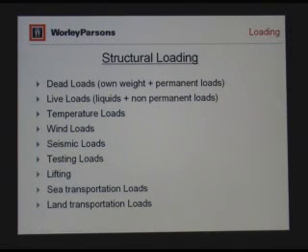But this has seen quite an evolution. Now, I think most of you are familiar with the seismic zones that we used to use in the Uniform Building Code. And as you may or may not know, the seismic zones are gone. They no longer exist. And what we have now are site-specific accelerations, the short-term and long-term, based on, of course, location. So it's very interesting, but it's quite tedious.